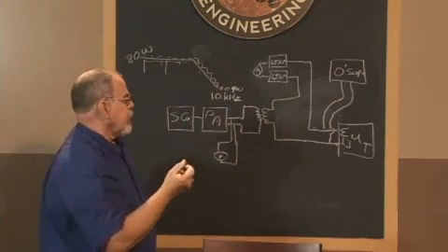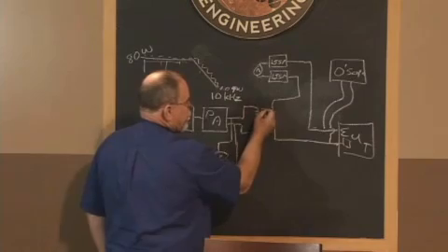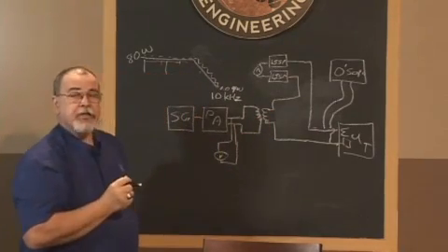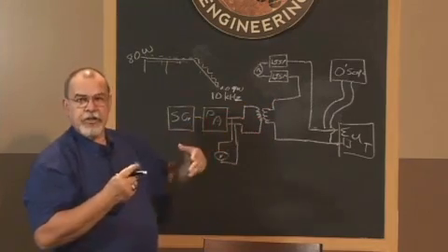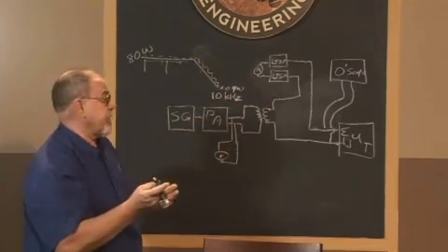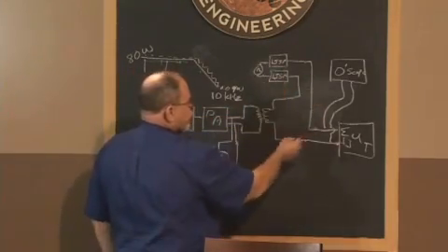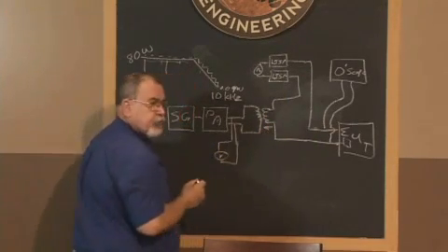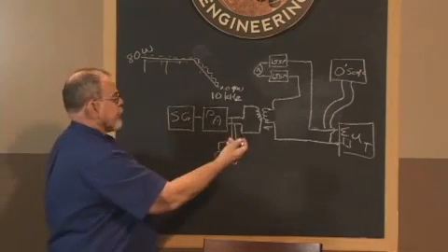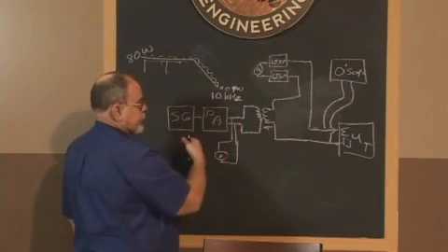Now this is problematic in some respects. The test article has 60 hertz or some frequency of power unless it's DC. When I have current flowing through this network, this secondary to primary coupling also occurs. So 60 hertz provides feedback back into this circuit.